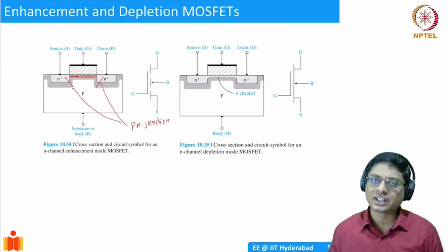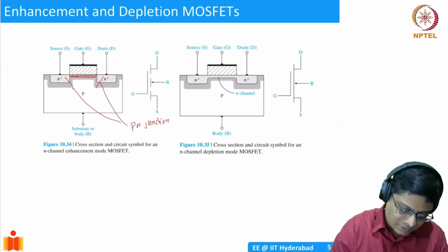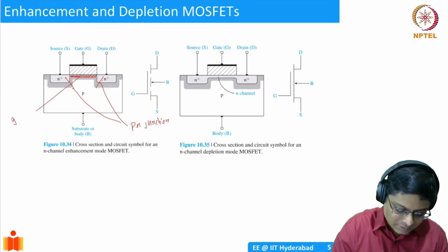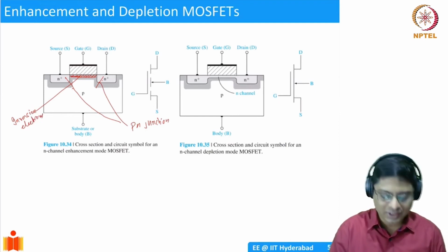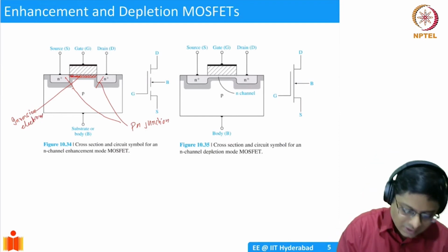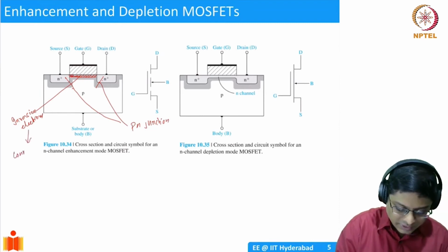And what is the inversion layer consisting of? Well, this is electrons, inversion electrons. So what does it do when you have an inversion layer like this just under the oxide? Well, essentially you're connecting source and the drain.